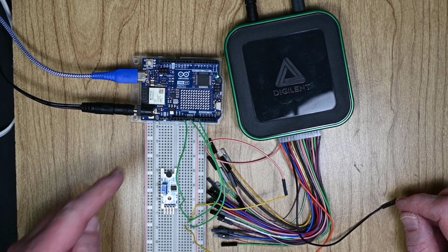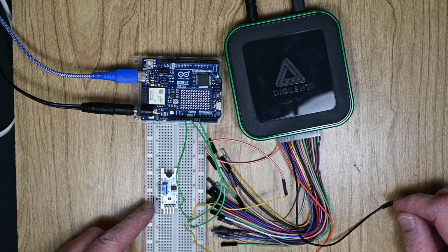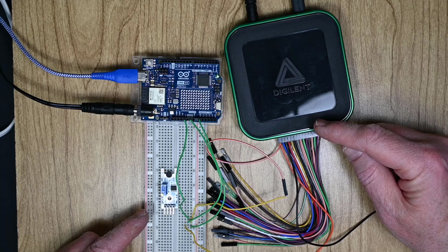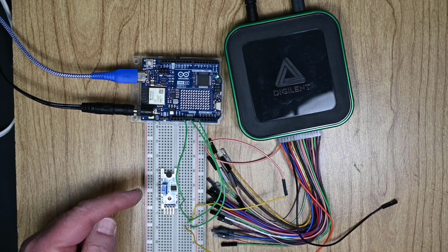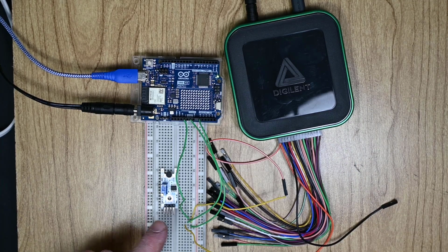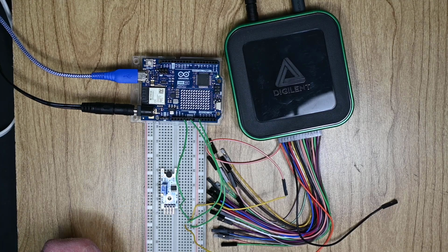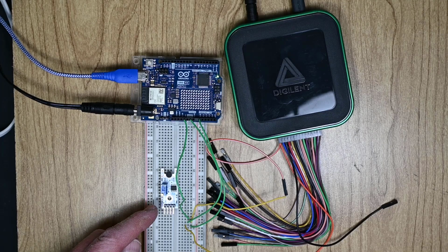The setup includes an Arduino, the audio module, and a USB oscilloscope so we can look at the signals. The audio module includes a microphone and an amplifier. It has both digital and analog outputs. The digital output will detect a sound level. We can adjust the level with a screwdriver that sets the value of a resistor.